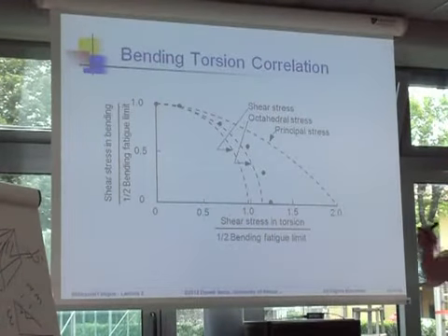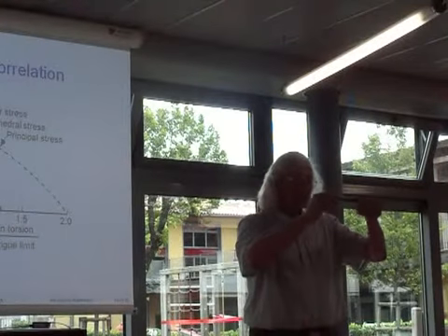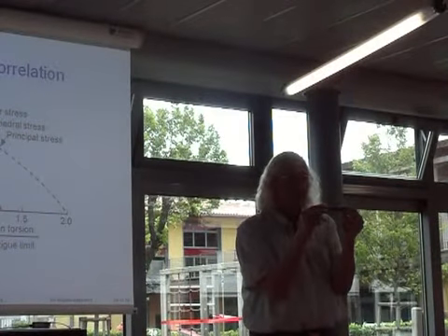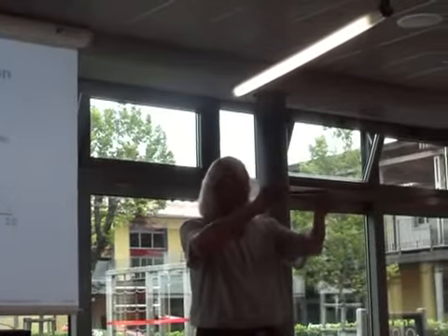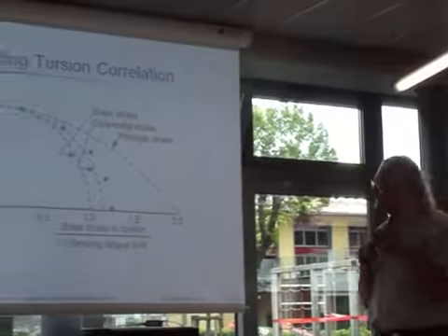So first we look at what the test data shows. And of course all of the early test data were combinations of torsion loading and tension loading. And that goes back to the problems really in power transmission. If you look at the early fatigue problems, they were all about transmitting power through a shaft with some gears or belts. And if you look at a shaft, the only way to load this is combinations of bending and torsion. And of course, if you do a fatigue test, it's much easier to do a bending fatigue test, a rotating bending test like Moore, than it is to do a cyclic torsion test. And so people wanted to know, what is the torsion fatigue limit, given that I know the tension fatigue limit? And then of course there were lots of tests where people actually tested in torsion and combined tension.